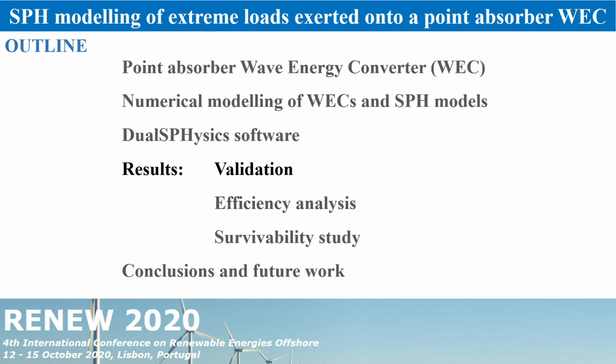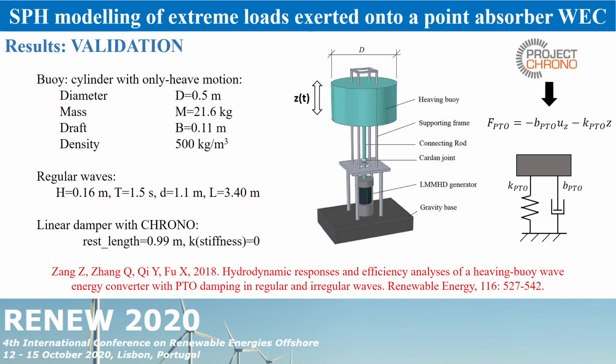Let's focus now on the results with the point absorber. First, the validation. We have followed the experiment described in the paper of Sang et al., where we have a heaving buoy connected to a rod with a PTO also attached to the bottom here. Here you can see the dimensions of the buoy, and we are going to reproduce these regular waves. The behavior of the PTO will be simulated numerically with Chrono. In the end, all these examples are using zero stiffness, so what we have is different damping. So we are going to simulate this as a damper.